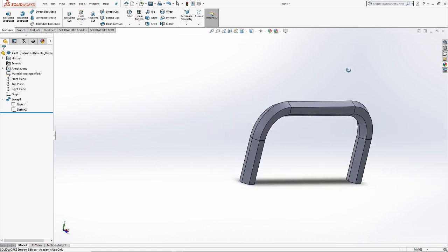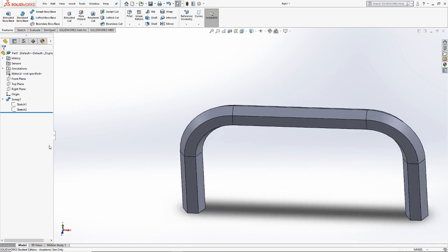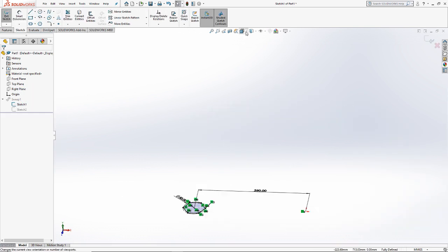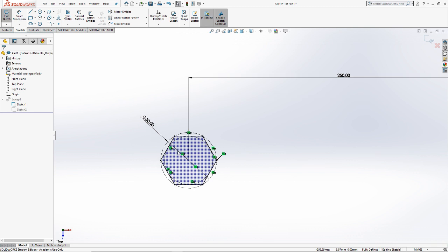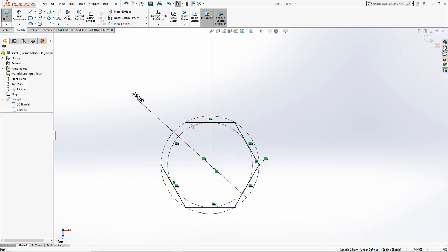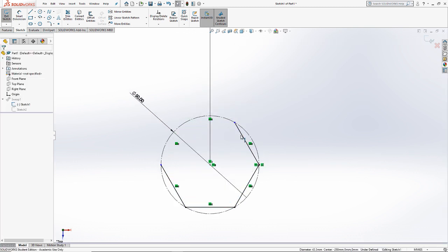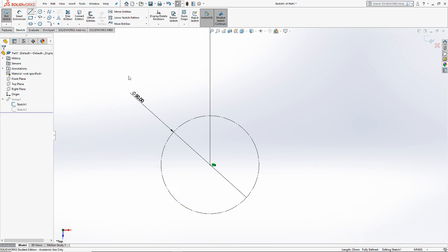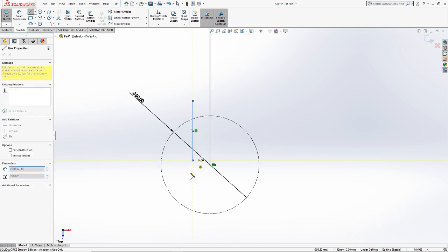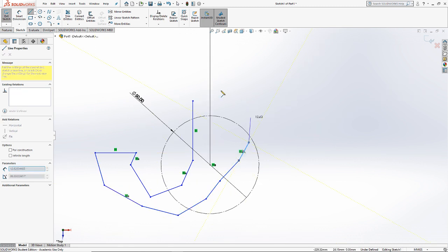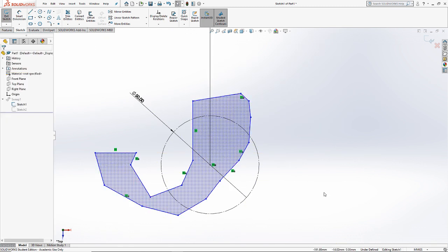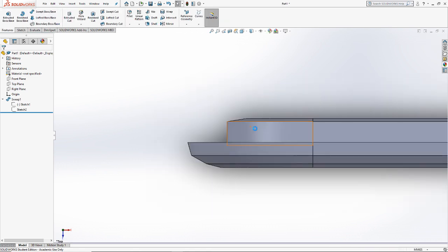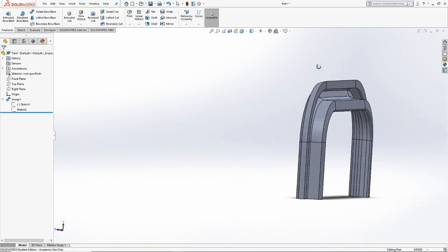Yeah, yes. Right. I mean, the world is my oyster at this point. Any enclosed contour would be okay. If instead of a hexagon, I wanted to go with like an octagon, which is cooler objectively than a hexagon, or if I wanted to like draw the shape of, I don't know, this thing, as long as it starts or ends on that path and is an enclosed region, I can create a handle with that geometry.